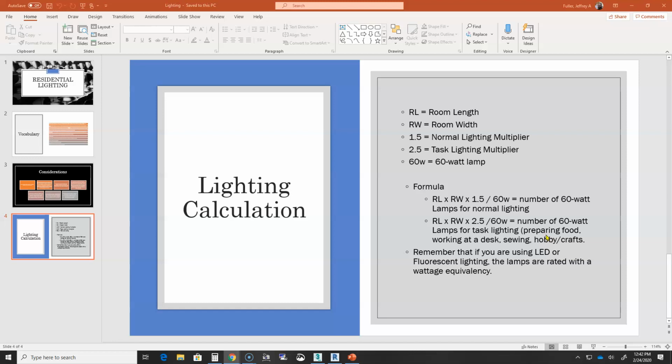So when you're coming to the design of, say, a residence, you're primarily going to be looking at those different effects that you can get from lighting, rather than providing strictly that minimum amount of light bulbs, 60 watt per light bulbs, for your light fixtures. Okay, but I was just showing you that because it is there. That is what we use in certain situations, especially if it comes to areas that need to be brighter. We might more or less use that task lighting formula to make sure we have enough lighting.